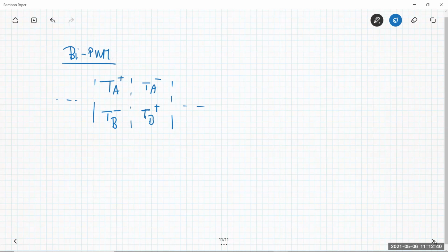There is not too much of the complication we had for the unipolar pulse width modulator. We have just these quantities for any time interval in T1. So the output voltage will be VD here or negative VD here. What about the output spectrum?